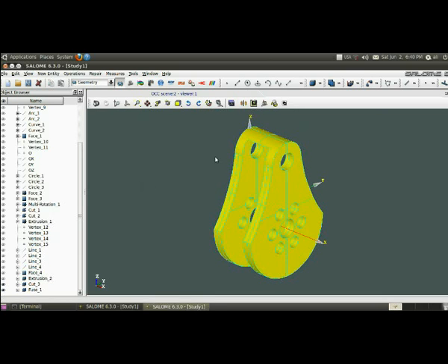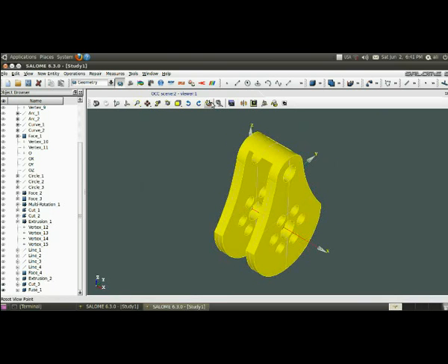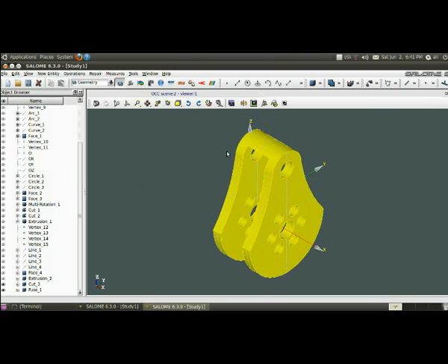Okay, at this time we have to make a boundary condition. The first boundary condition is related to the top hole for a fixed condition, and then we have to apply some load on the main shaft axis, and after that we can make an analysis. Okay, I have to go to the new entity group and create a group.